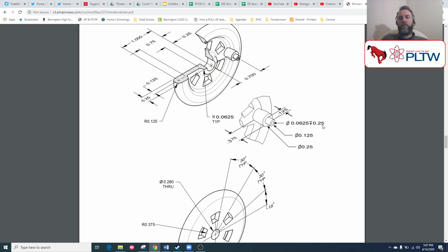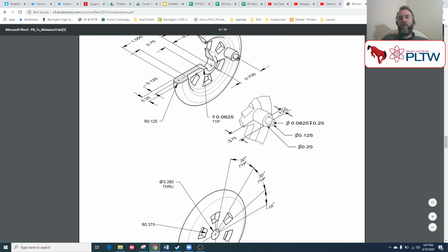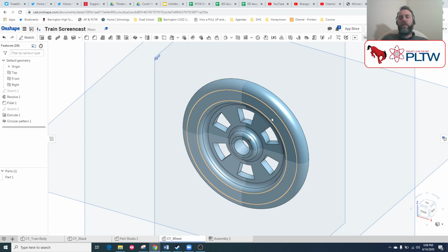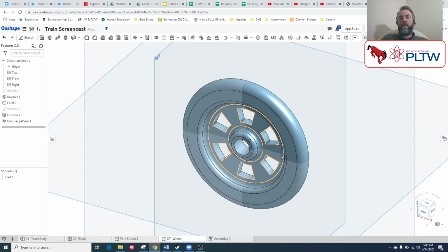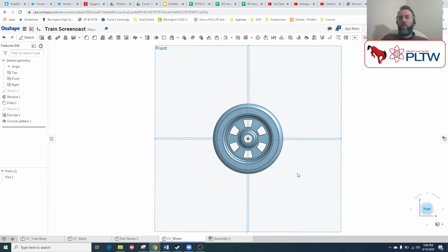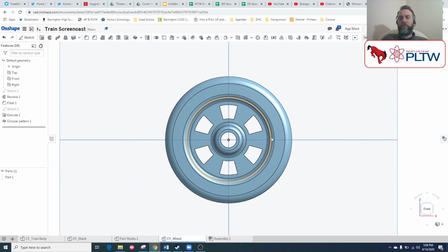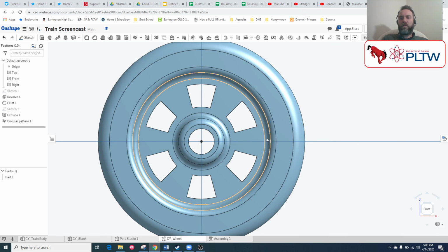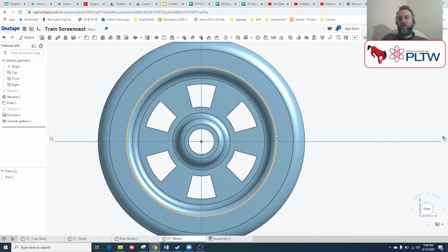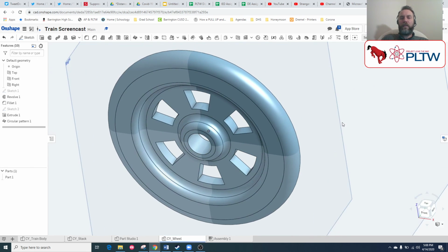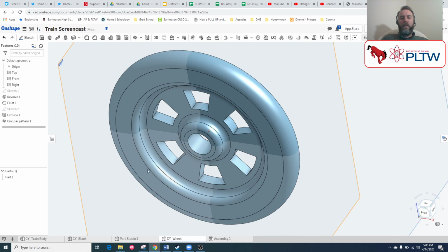So 3 circular features right there on one spot. If you start your sketch on the front plane, make it right horizontal over here, it will end up intersecting with this fillet feature here, that's fine. It will build correctly if you do it correctly. So there you go. That's as much as I'm giving you on that one.